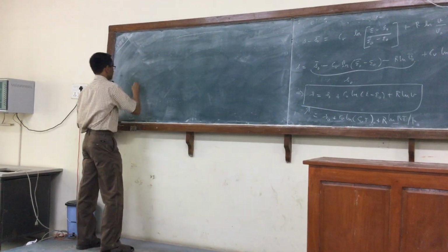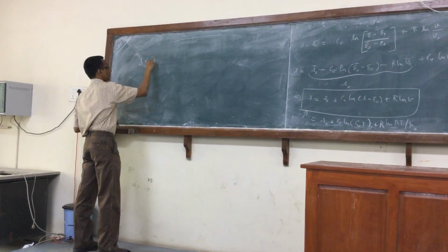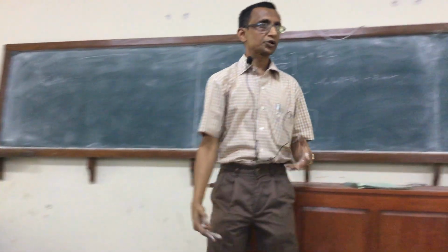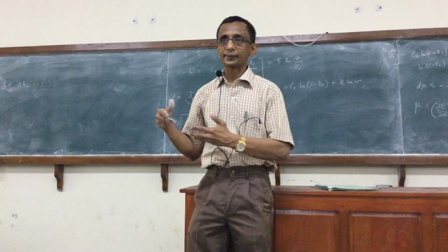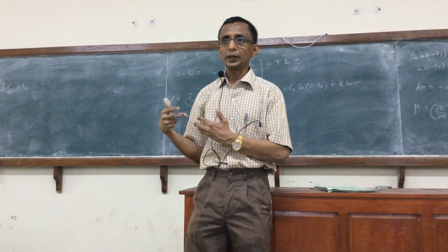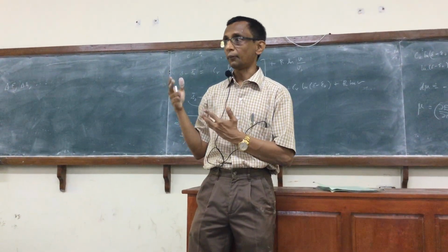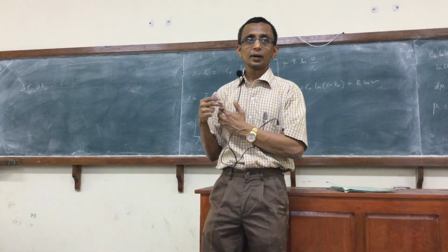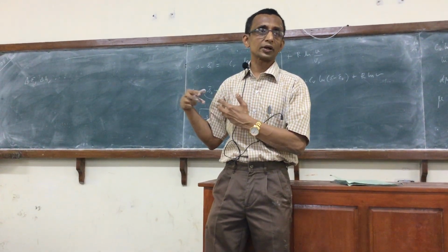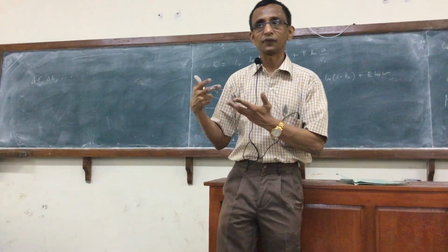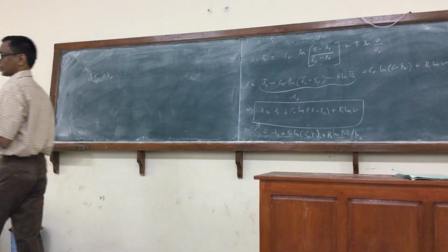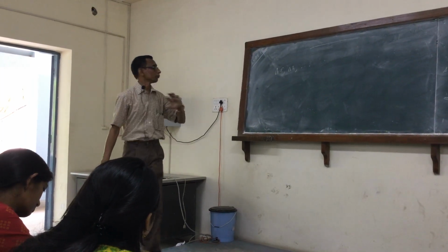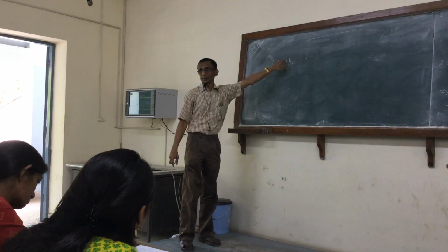And so we move from this and go back to the original problem that we proposed, namely being able to calculate changes in properties between two states. Because the whole idea of developing the differential coefficients of H, S and so on in terms of V, T and P was to be able to integrate them and construct changes in properties, which we also said are related to the change in internal energy in an adiabatic process, will give the work done or the negative work done by your body and so on. So there are various other motivations for having to calculate this.